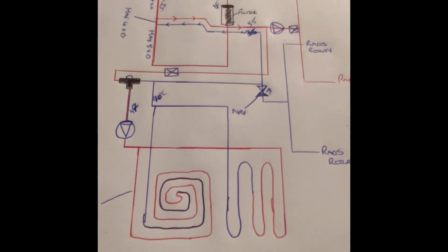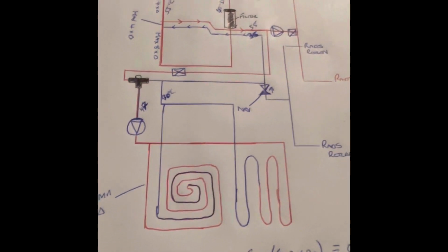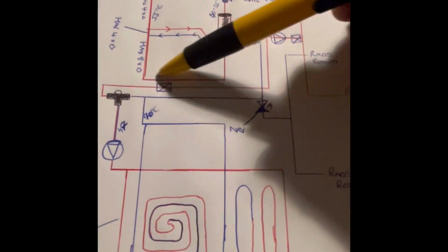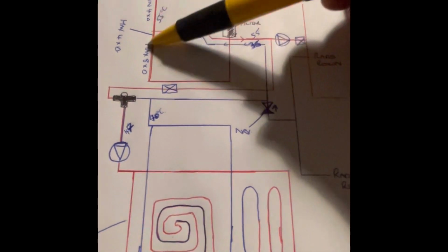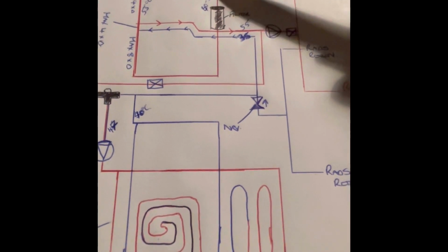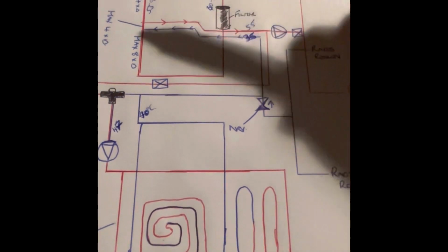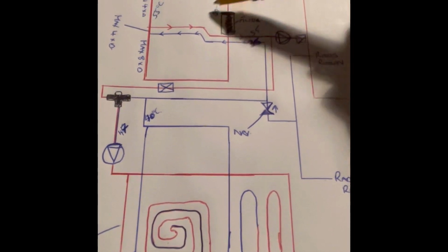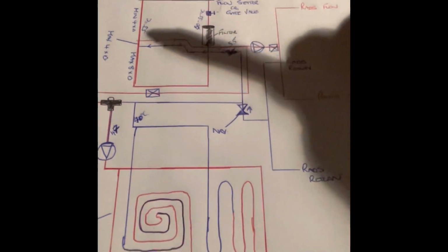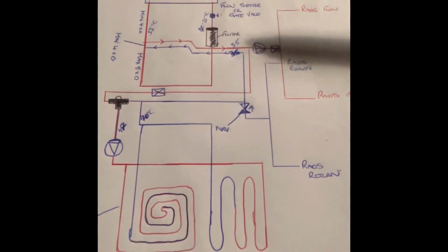So that's how I did my system. Just some other little bits I'll touch on while I'm doing the video. How this basically works is that the pump inside the boiler runs this primary loop here, and it'll just circulate there and look after itself. So that should maintain, realistically, a DT of 20 degrees. DT means the difference between the flow and the return. So all heating systems nowadays are designed for a DT of 20 degrees, which will change. It is going to change. Some are designing for a DT of 15 at the minute.